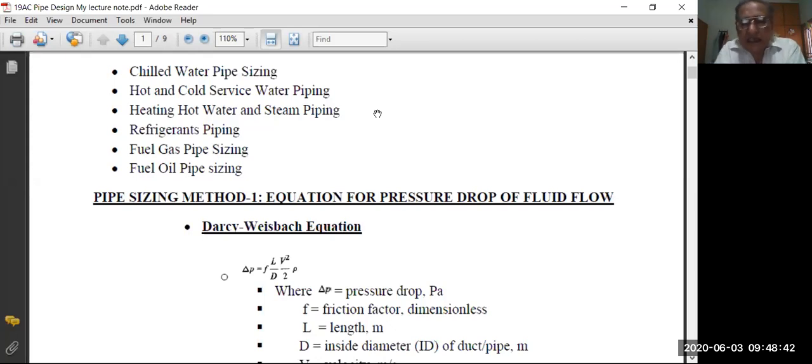You will learn about this in this lecture. The engineer does not only require to design these chilled water pipes. HVAC duct is also his responsibility, and we learned that yesterday. Not only chilled water pipe, it may be hot water pipe. If it is a round the year cooling system with a boiler or hot water heater in the system, then hot water is circulated through the coils in the winter season. In that case, hot water loops are also to be designed by the HVAC engineer.